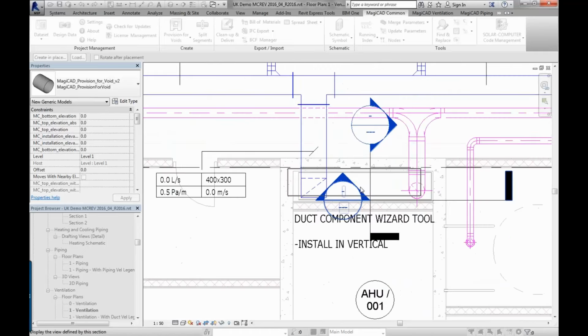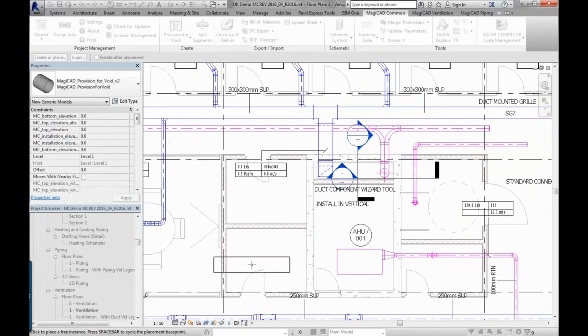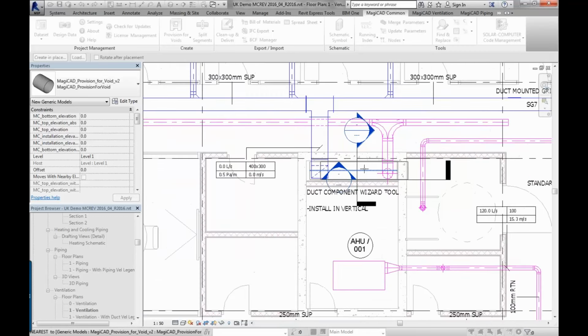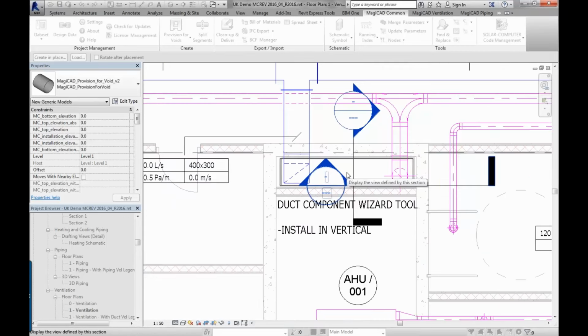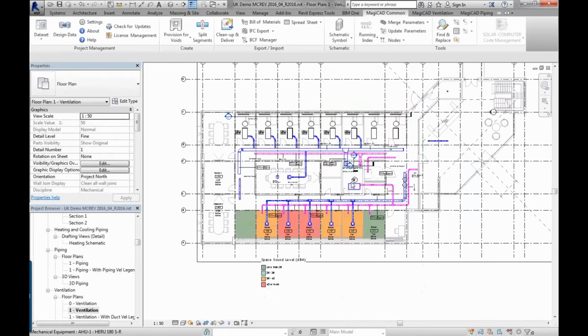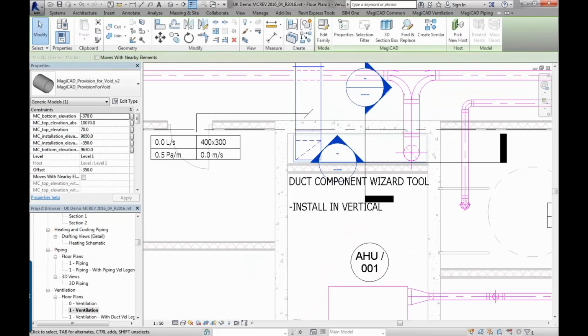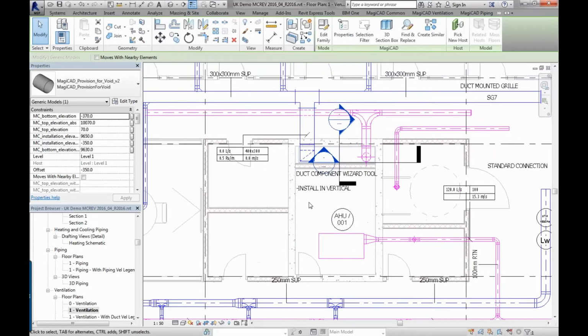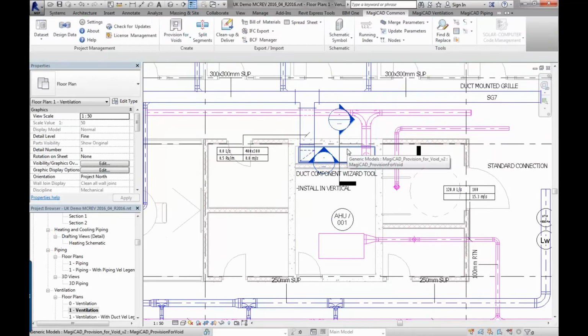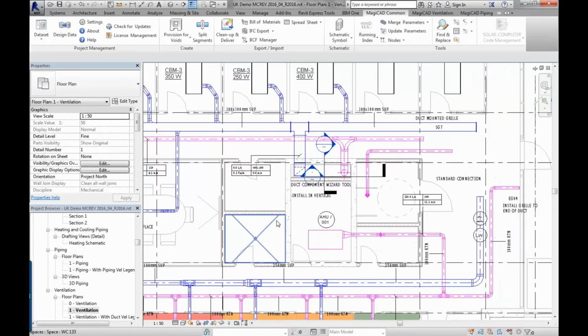So you can just click in here, click in there, it doesn't matter in this particular example. So I'll just select it into there like so, and just plonk that in there, and you'll see that we now have this void created in here. That's actually not true. It's the request for a void. So the MEP engineer is creating a request which needs to be agreed with the architect and structural engineer later, and we can see that process as the webinar continues.